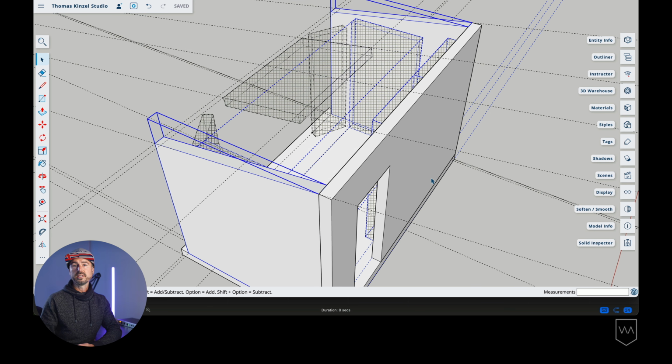Now let's talk about the game plan for treatment in the room. Basically, I'm going to load in as much broadband absorption as this room can take. And we of course are going to have several constraints. One constraint we have is the size of the room, right? The amount of acoustic treatment that you need to treat bass frequencies is typically large, but we can definitely make a substantial improvement. And part of that is just getting a lot of absorption into the room to begin to take some of that bass energy and control it.